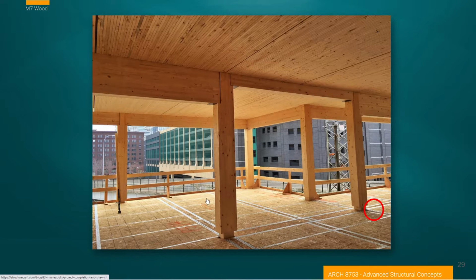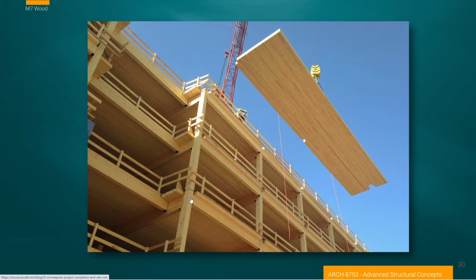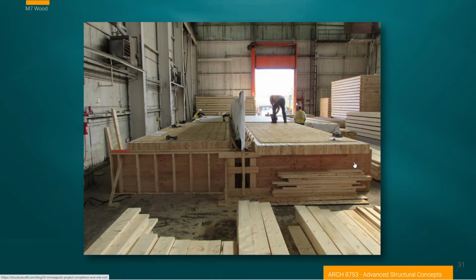And where I'm going with that is that we seem to be using a great deal of wood in these construction systems. Here's a great image of a large slab going in, and you'll notice that it's notched. It's actually spanning over a beam system, but it's a continuous element. It's probably done this way because it's convenient, or simplifies fabrication and removes field joints between the spaces, and allows these two, because they're continuous, to perform better under load.